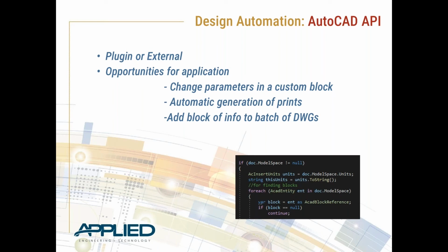Thank you, Jerry, for going over the iLogic rules and the configurator for us. So if we have some function that we've built, now we want to automate it further, maybe let's make 1,000 of those wheel models. How do we do that? Well, Autodesk is kind enough to provide us with a few different public interfaces, so a programmer can write functional code for their products. These are called APIs, which stands for Application Programming Interface, and these are pretty much libraries of defined functions that you can call, and the programs know how to respond to them.